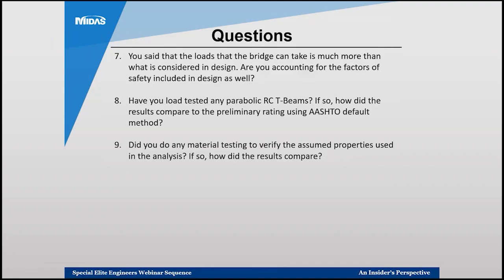So this is your M nominal, or the nominal capacity of the slab. What we are looking at is the demand side. Now we're assuming when the slab is acting as simply supported, the demand is 100 kip feet. In reality, the demand is 60 because of the two-way bending action and the negative moment. So what we're mainly assessing is the demand on the beam or the slab, not the strength of the slab or the beam. The strengths are unchanged, and I don't think the concrete strength will have any impact on the flexure strength of the beam.